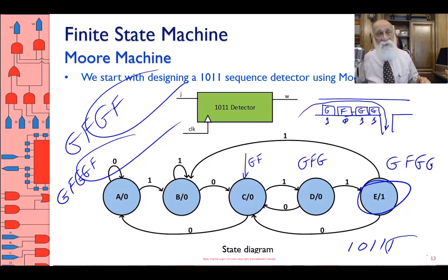That's my state diagram for this little controller, which I'm referring to as a sequence detector. What's so good about the sequence detector is that it's easy. It has one input, it has one output, and it has 4 or 5 states, and therefore it's manageable manually.